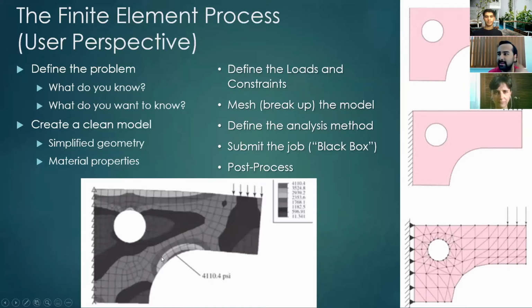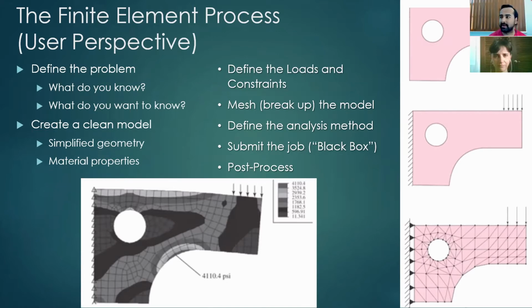So you should intuitively expect there would be a stress concentration here. Now, maybe this amount that you're seeing here is below your threshold, in which case that's great. Or maybe this amount is not good, so you're going to go back and adjust the geometry and see what you can fix and edit to improve this model. And then you just rerun your simulation over and over again until you meet whatever criteria.